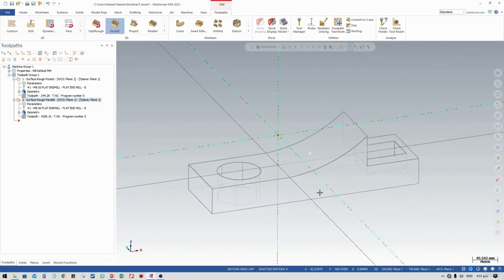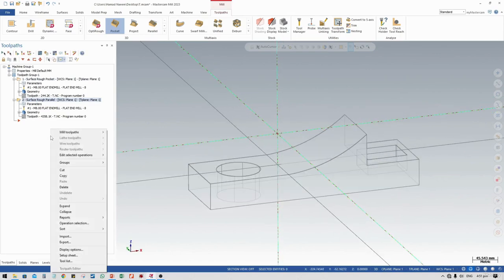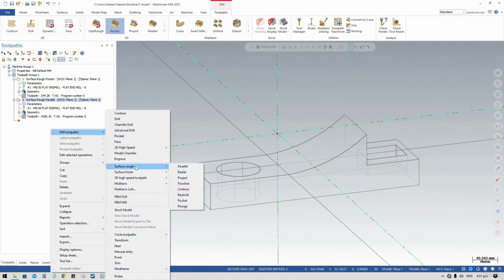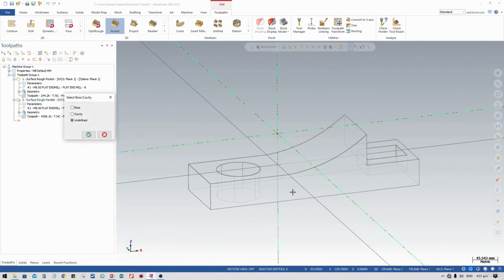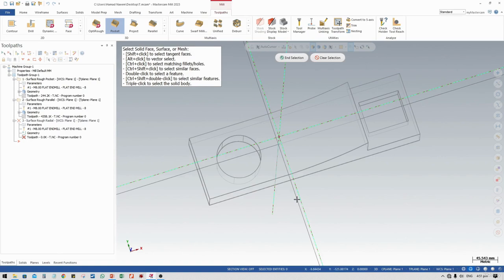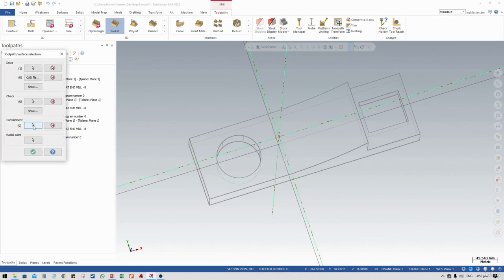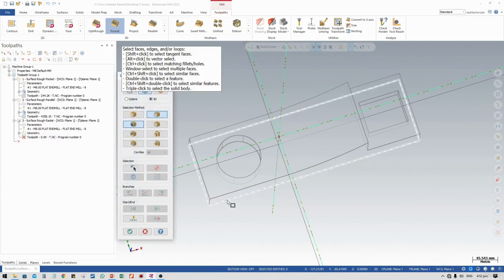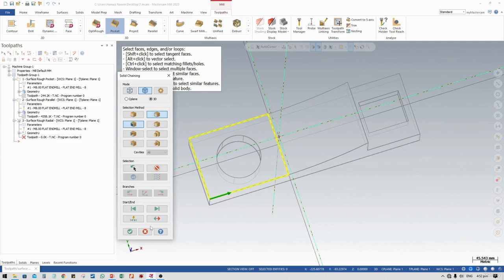Next, let's move towards another operation, which is all about the radial position. The cutting operation being done on this will be in a clockwise direction, just like the seconds and minutes are in a radial, circular position. So I'm going to machine that area. Just select that area. And how about the containment? Yes, just select this edge as a containment.